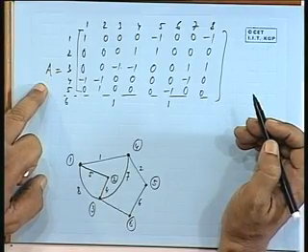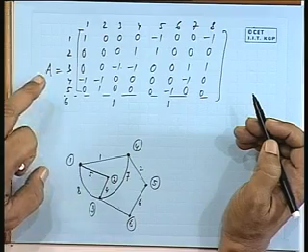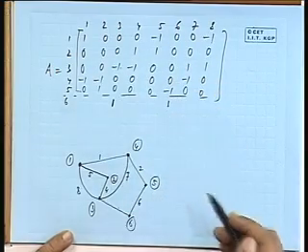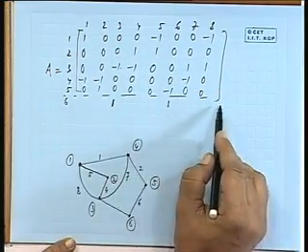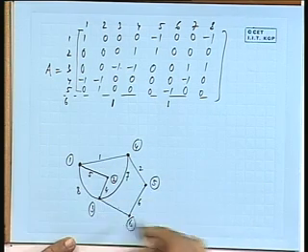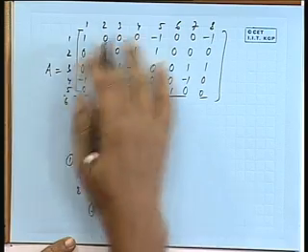Then you have to select whether it is an A or AA matrix. Suppose it is given as some incidence matrix. Is it the complete incidence matrix or the reference matrix, the normal incidence matrix that we deal with without the reference? Since in these two columns we find these two elements missing, there is another row, another node, the 6th node. So, we plot accordingly. Okay. So, this is the complete graph.